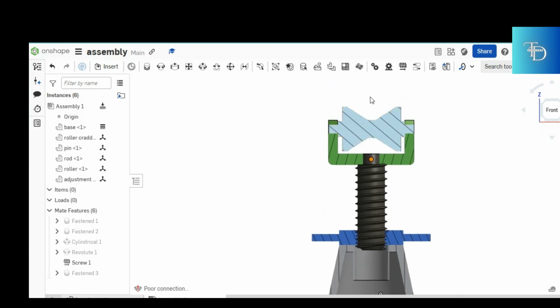Now, even on the top side right here, if there was a part that was in contact with the roller itself, the hatching lines were gonna change direction to that side. They were gonna lean to that side right there, which is the direction that is opposite to these lines right here, because these sectioning lines go in that direction from the roller.